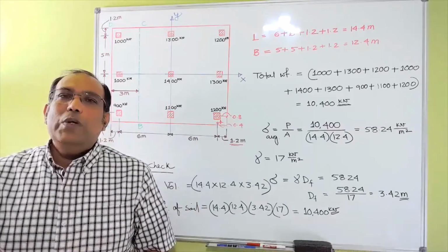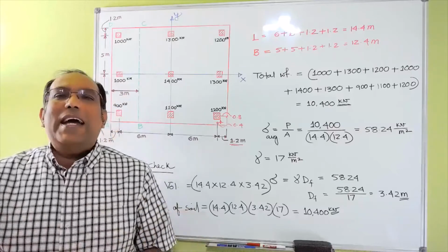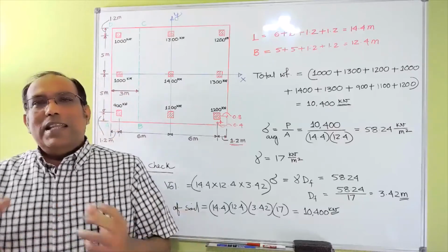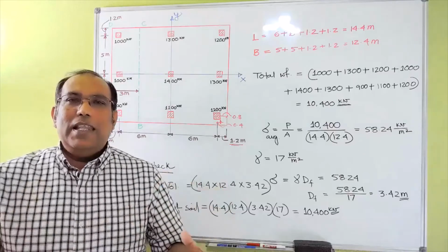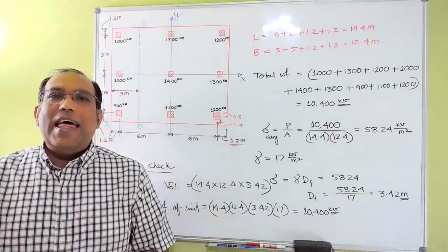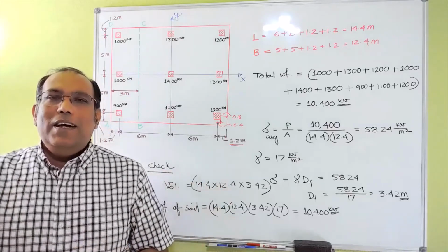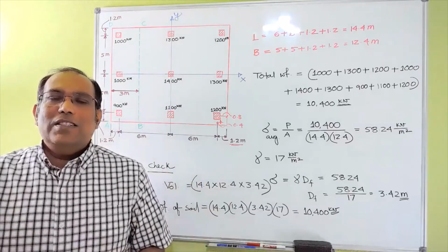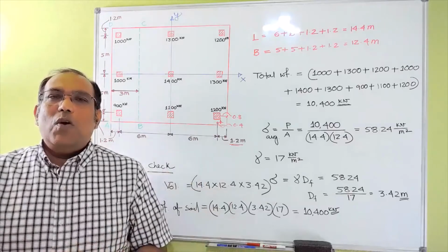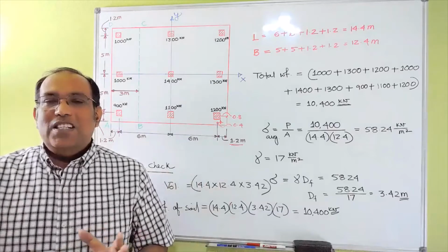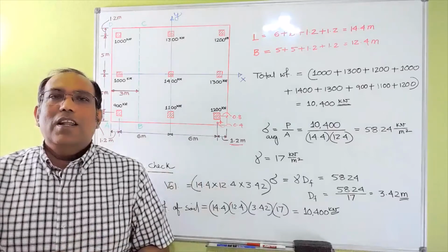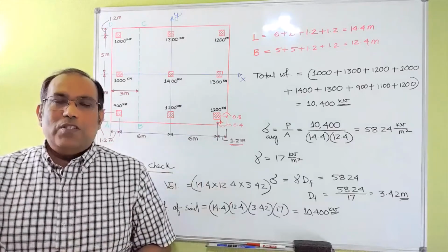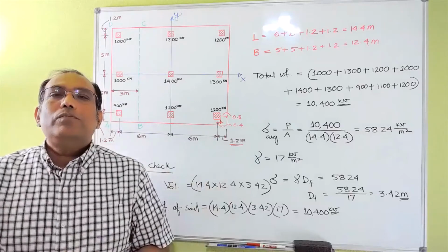So we are not going to put the soil back there. We are taking that soil out, making the structure there, and the weight of the structure is the same as the weight of the soil we took out, so no additional settlement or no additional effective stress on top of the soil, okay?